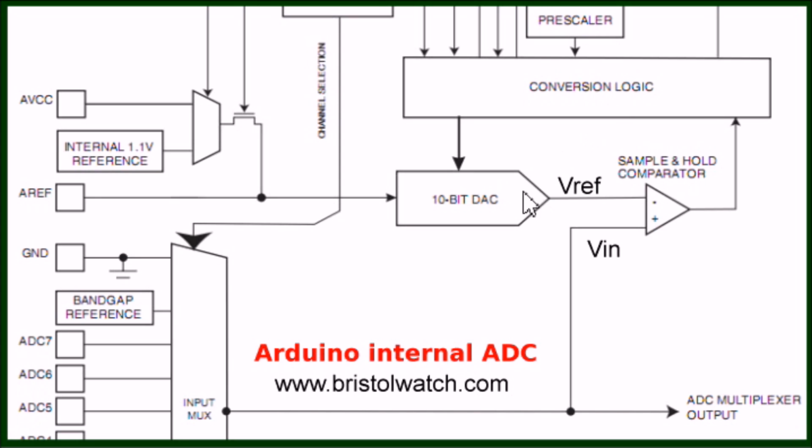But basically, if Vref is greater than Vn, it probably does some kind of logic change. And the number that you get back when you do an analog read is that 10-bit number from 0 to 1023. So that's how your analog to digital converters work.